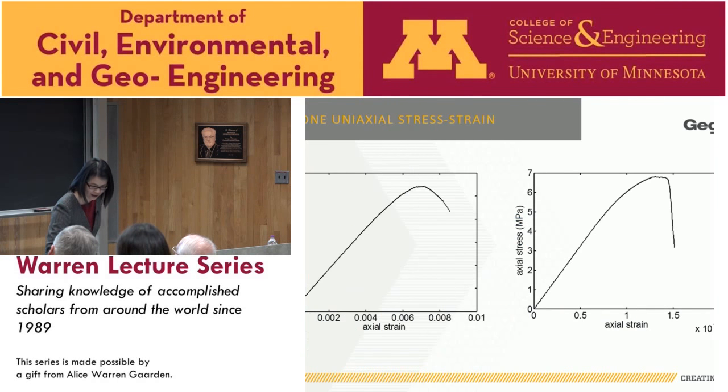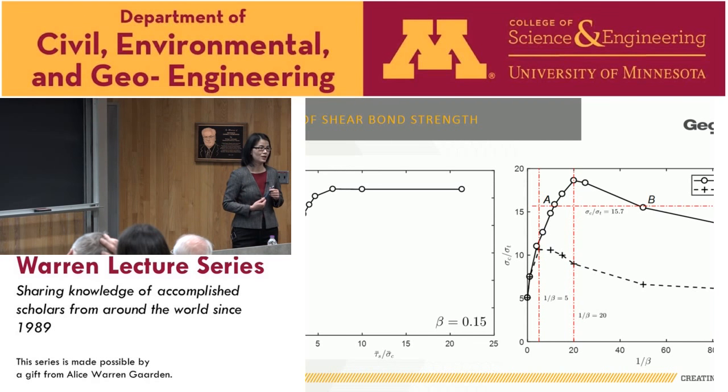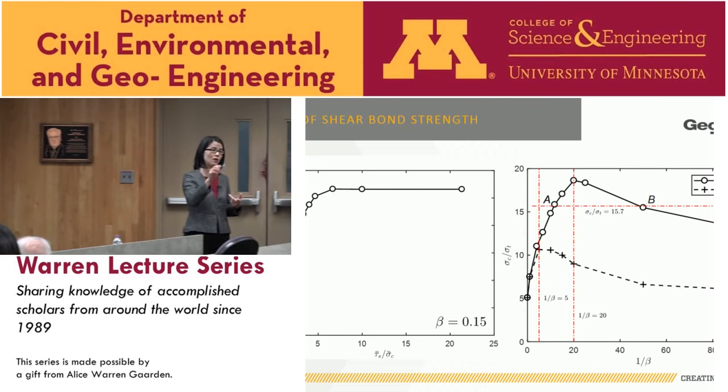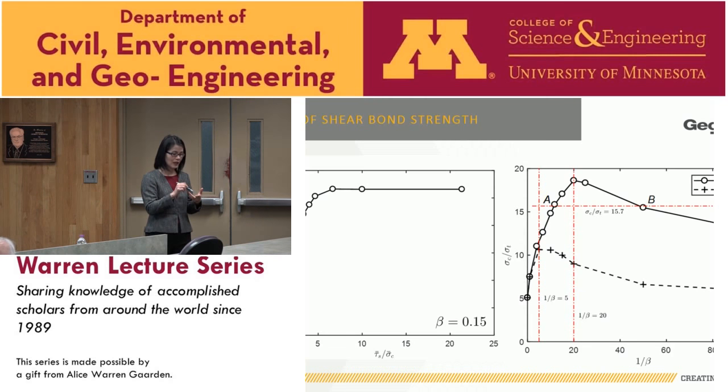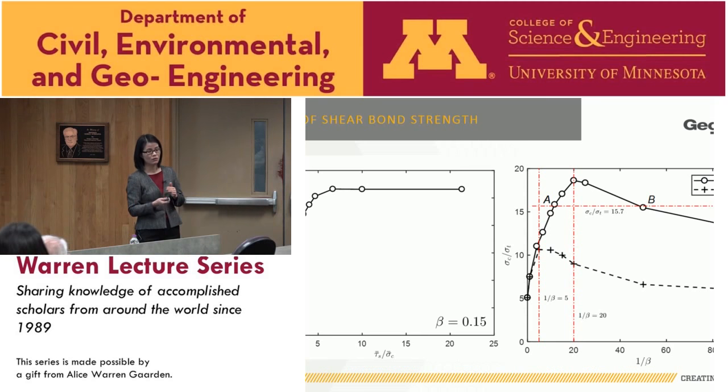Now, we've actually done work with the shear bond changing, using two approaches. One is just to bring down the number. So in shear, it's still elasto-perfect brittle. Second is to have softening in shear as well. But the global picture is not changing. Adding shear would actually bring down the strength ratio.